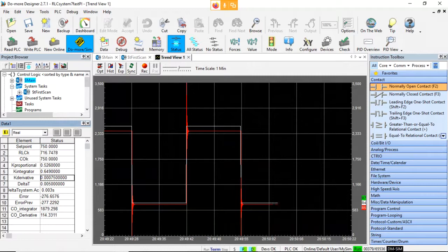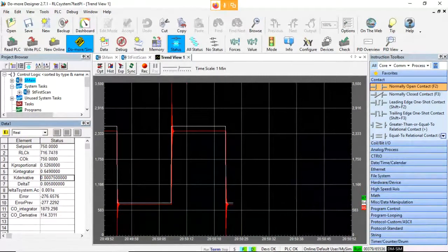Remember, this derivative piece I was dividing by 8,000. And so my derivative term is actually just very, very tiny here. It's 0.000, that's 3 zeros, and then 75. So it's a very, very small gain. Now these are just gains. These are unitless gains, so they don't have like a voltage or anything of that nature with them.